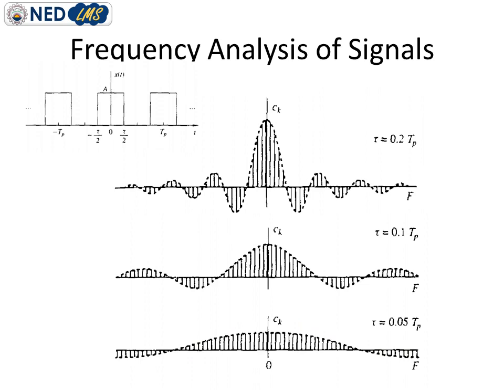The next thing you can observe is that we are not changing the time period of this waveform, so the spectral spacing and spectral density of these three plots remain the same. There is no effect on the spectral spacing or spectral density of these frequency domain representations, as we are not changing the value of the time period.